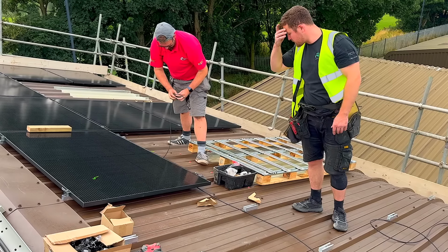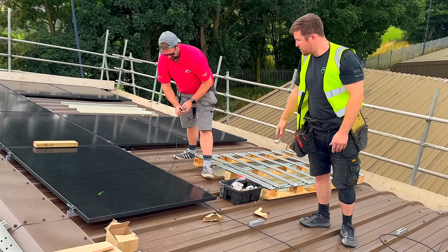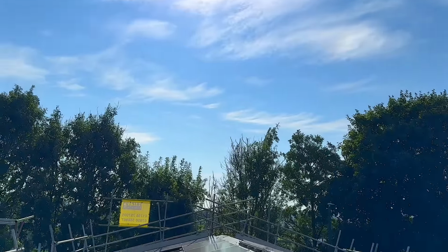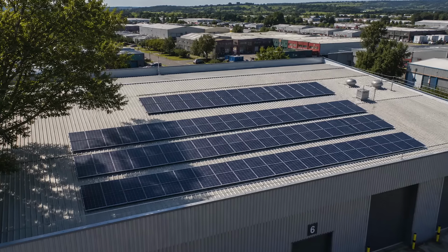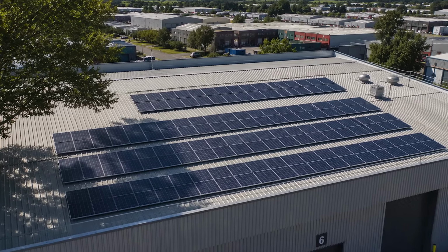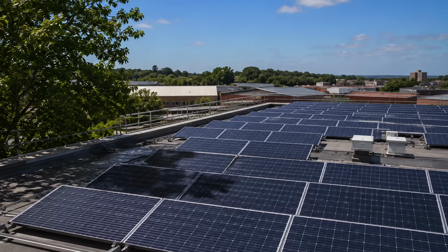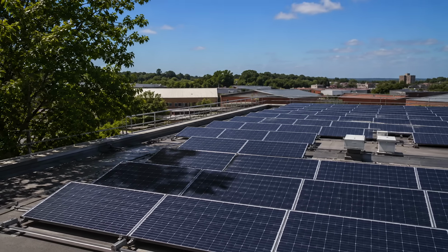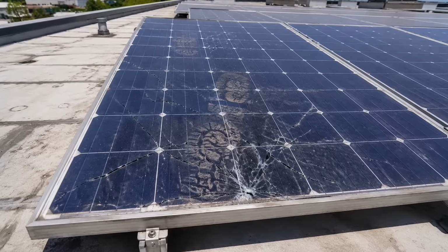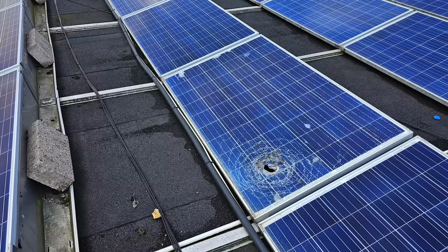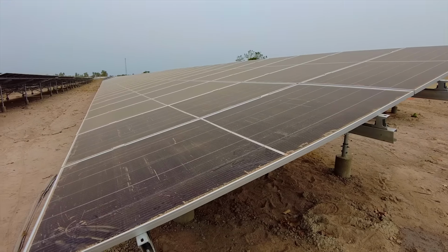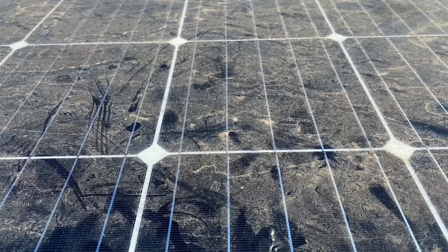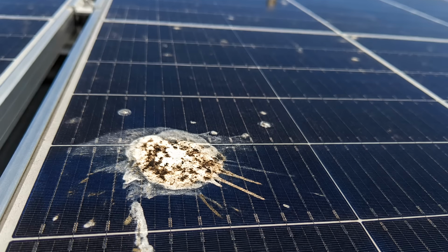Of course, the real world doesn't play nicely, because while temperature and light shift the curve in predictable ways, there are plenty of things that don't follow the rules. Take shading, it only takes a shadow across part of one panel, and suddenly the whole string starts to struggle. Then there's physical damage, panels walked on, cells cracked by hail, one weak panel dragging everything else down. Dirt-induced issues, dust across the surface, debris collecting at the edges, and of course pigeons leaving their mark.